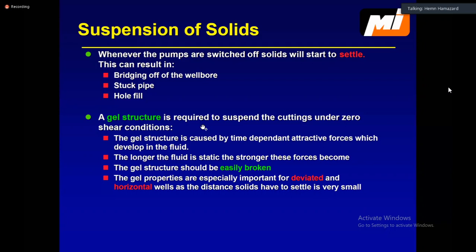You stop pumping. You must have a proper mud to suspend all the cuttings within the mud so they don't fall down. If they do, then you are going to end up with what they call fill at the bottom of the hole. You always have problems going in and coming out if you don't do so.